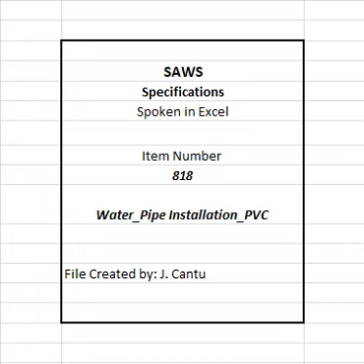D. Submit manufacturer's certifications that PVC pipe and fittings meet requirements of this section and AWWA C900 and AWWA C909 for pressure pipe applications, or appropriate ASTM standards specified for gravity sewer pipe.